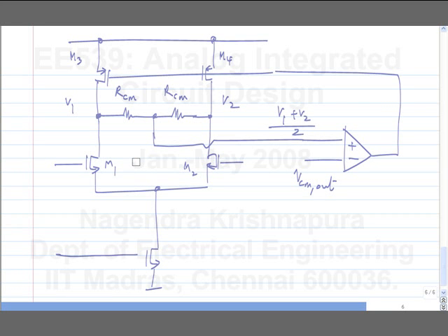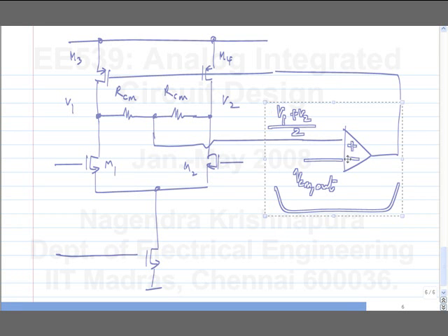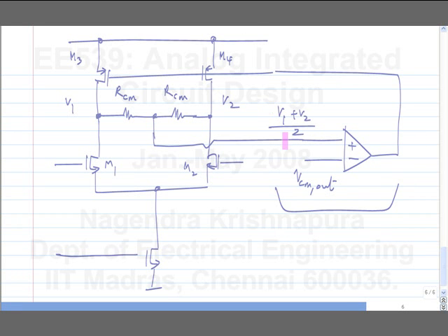Now, what is a simple thing that we can use for this op-amp? Direct connection. I want a positive gain from this point to this point. Okay, I'll settle for a gain of 1, just like I did for the diode-connected transistor, right? I want to sense at the drain and feed it back to the gate. Then I settle for just connecting the drain to the gate.